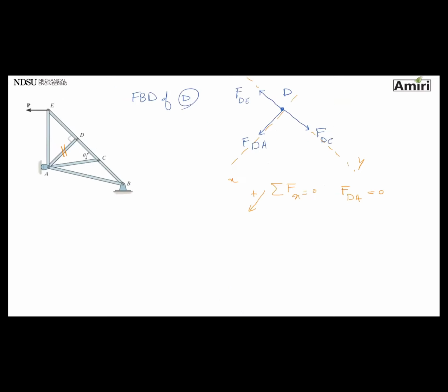Same thing here. If you draw a free body diagram of joint C, this is going to be 0 too. So your truss is going to be pretty much like this. Again, these two are totally equivalent and similar as far as loading goes. And this is still a truss. It's 3 members pinned together, and the loads are only at the end.